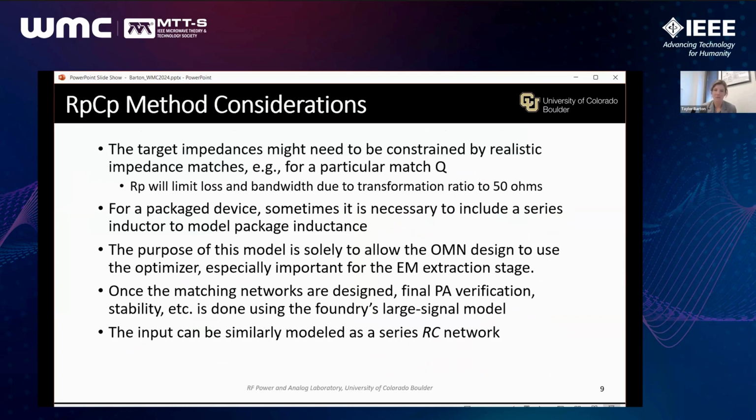You can also refine things by, for example, limiting the Q of the match that you're willing to make because of your process or frequency, or the combination of your process and frequency for MMIC. And then you can do a similar approach, by the way, on the input side, but of course the input to the device is best modeled as a series RC because of the physical structure of that.